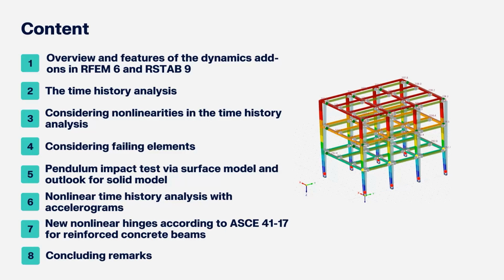In the next step, we'll also go in the direction of the so-called performance-based design. We're going to see it on the right-hand side of this slide. We're going to see acceptance criteria given in colors and everything. This is also then the introduction for some other new advancement. I'm not going to relate it to the nonlinear time history in this webinar, but we also introduced new nonlinear hinges according to ASCE 41-70 for reinforced concrete beams, which are also shear force dependent.